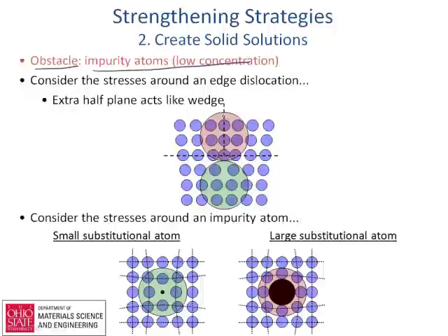And so here's what the material looks like. We put a dislocation in it. You can see this is the end of this edge dislocation. This defect goes into the plane of your computer screen, goes back that way. But you can see that this is very crowded up here. And then as these planes come down, there's kind of some extra space here.